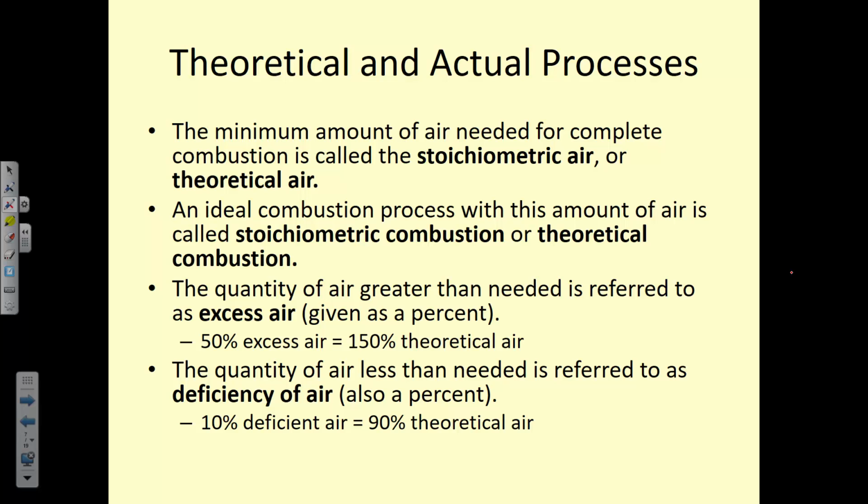If we have greater than the needed amount of air, it's referred to as excess air. And in some cases, having excess air is a necessity in order for this combustion process to be assured to be complete, because the theoretical amount of air may be insufficient in a case where there isn't enough mixing, or if your temperatures are slightly too low. So in some cases, the excess air is necessary in order to assure complete combustion.